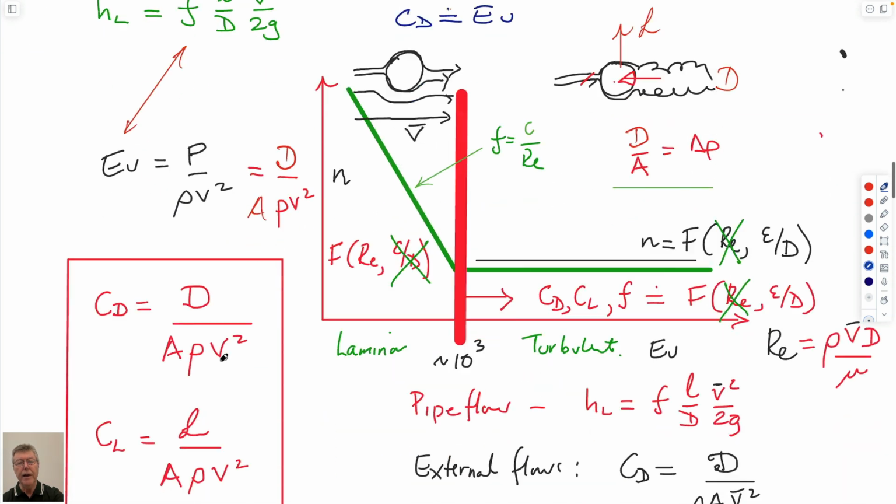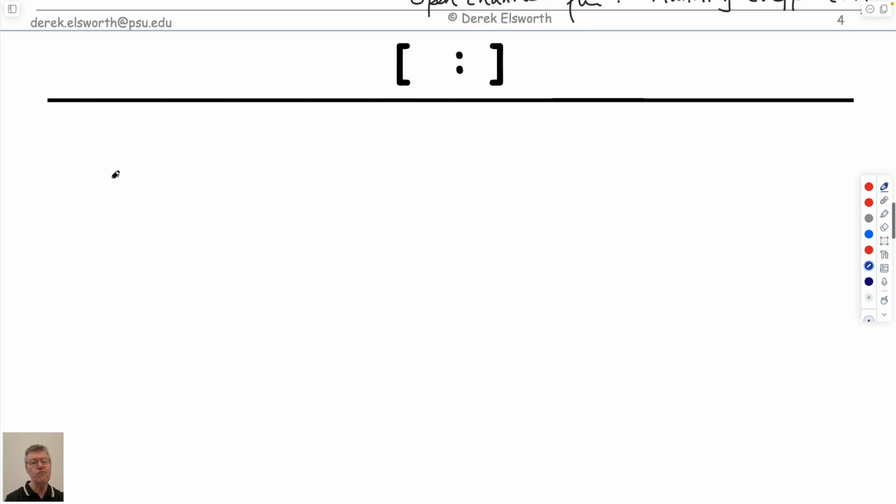If we use Buckingham Pi, and I'm going to go down here, Buckingham Pi says that of these variables, let me just write it as pressure. We have pressure, we have velocity, density, and we have viscosity. And then we have the geometric terms, which are length, diameter, and roughness, which we've kind of used. And we've used these last 3 to give us length over diameter